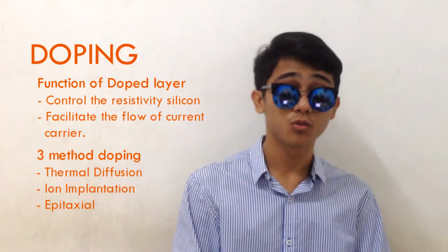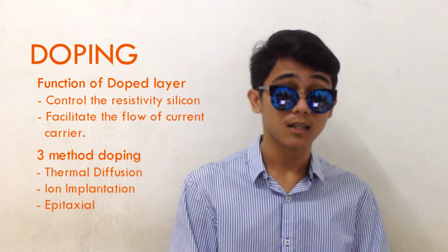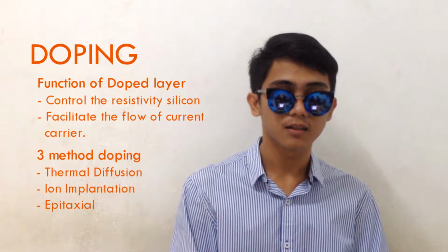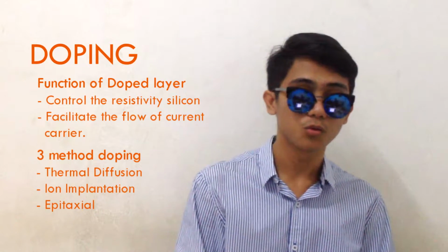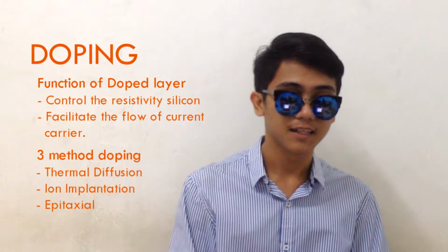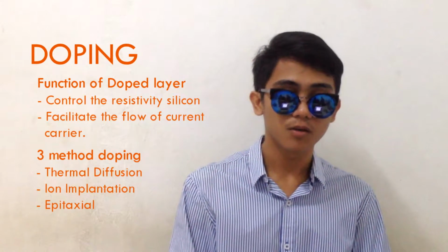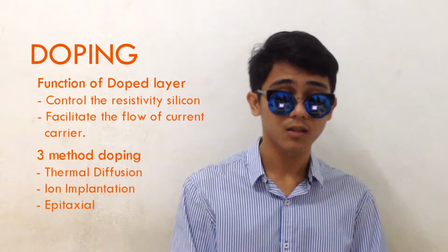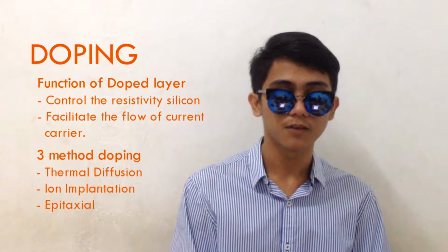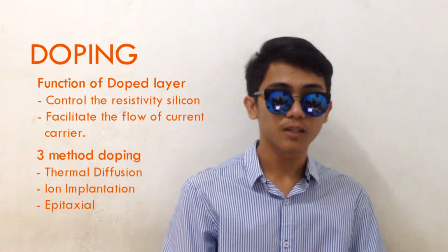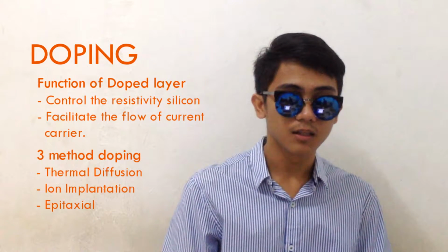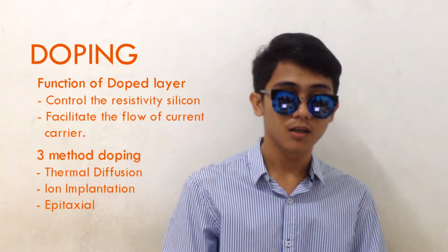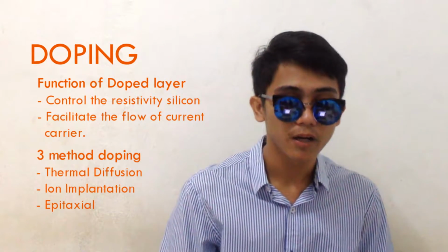The wafer is exposed to dopant, and next, the wafer is heated at a high temperature of about 1000 to 1200 degrees. With time and temperature, the amount of dopants is controlled. Then drive-in: no more dopants are provided, and the dopants are driven from the surface into the wafer by controlling the temperature and time.